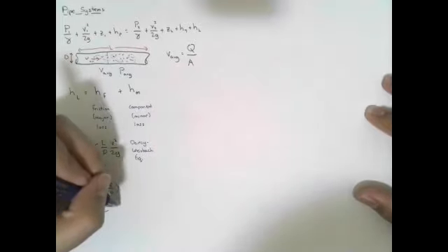Now, this friction factor is a function of the regime of the flow, which is quantified by the Reynolds number, and the relative roughness. The Reynolds number, we've already seen this before several weeks ago, is simply velocity times diameter over kinematic viscosity. Let's recall, this is the Greek letter nu, which is the kinematic viscosity.